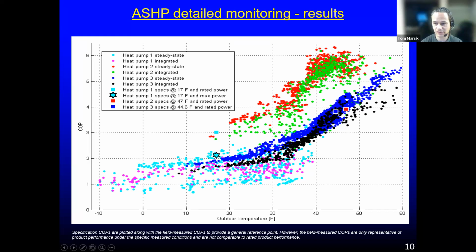Unfortunately, we cannot draw any solid conclusion from that, because with this heat pump, a ductless mini split heat pump in Dillingham, Alaska, we noticed the opposite. So that's this blue and purple dot series. We noticed that with a lower level of thermal loading, the coefficient of performance actually went down. So this triggered a research question that we looked into later, because again, it's important to understand how to size systems and how to operate them. I'll get to that later.